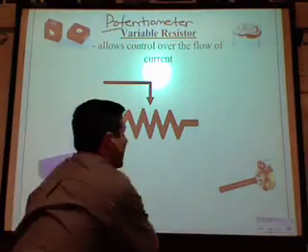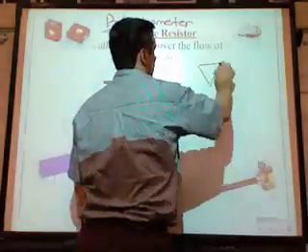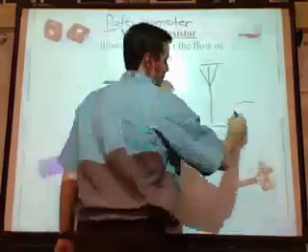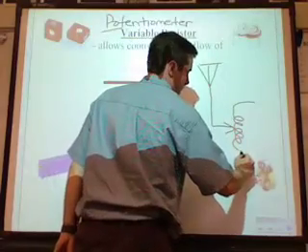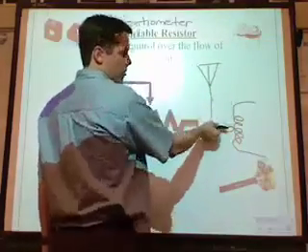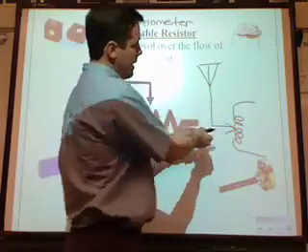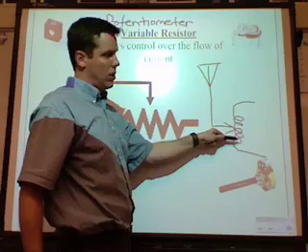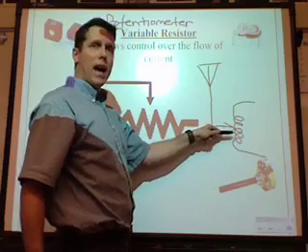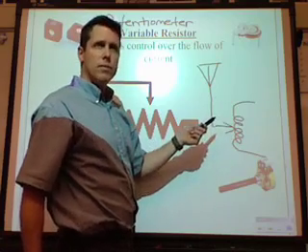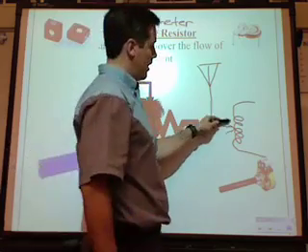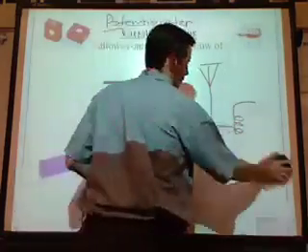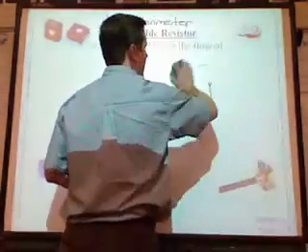And if we control the resistance, we can control the flow. If you think about it, remember our schematic for the crystal radio? What was this part? And what's this part? Coil. And remember how we had it drawn like that? Well, what that indicated is that I can change where that antenna connects to the coil. And by doing that, it's the same as doing what with the radio? Tuning it. By adjusting the length of the coil, where it's connected to the coil, I can tune it in. Well, that's the same thing we're seeing here.